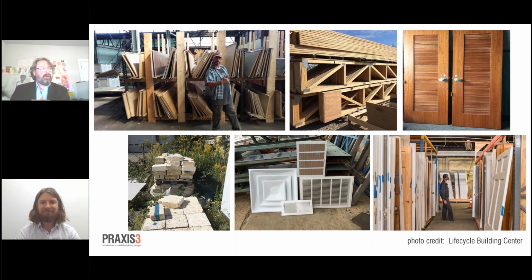In fact, I'm told by the masons that when we do that, about a third of the brick can be actually reused in the new building. About two thirds of it are lost just in the process of trying to knock all the mortar off the brick. So one advantage of upcycling pavers is that oftentimes they're loose laid or in a sand bed, and those can be taken out and very easily reused in another situation.